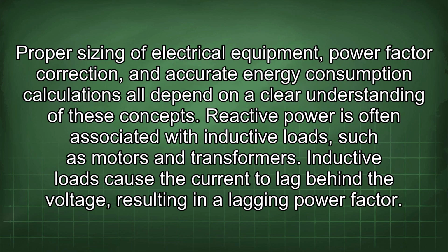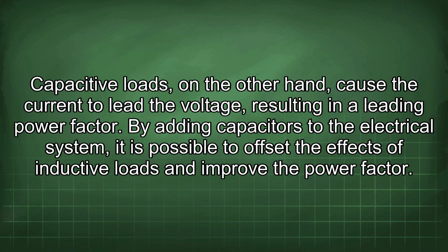Proper sizing of electrical equipment, power factor correction, and accurate energy consumption calculations all depend on a clear understanding of these concepts. Reactive power is often associated with inductive loads such as motors and transformers. Inductive loads cause the current to lag behind the voltage, resulting in a lagging power factor. Capacitive loads, on the other hand, cause the current to lead the voltage, resulting in a leading power factor.